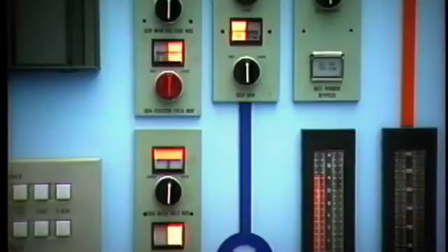All of these components of the static excitation system are normally located in the excitation panel close to the generator. Of course, the auto and manual control inputs are also located on the operator's panel. Another type of excitation system often used is known as the brushless exciter. The exciter is actually a small AC generator which is built on the end of the generator shaft instead of collector rings.